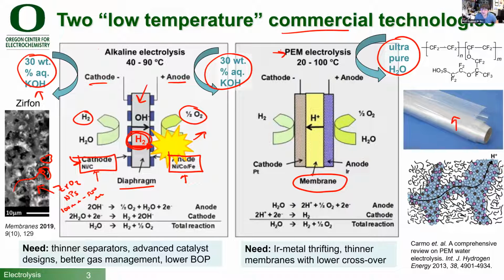It's a polymer that's used in proton exchange membrane electrolysis because it has strong acid groups bound to a fluorocarbon backbone. And those strong acid groups create water channels that are inside the pores here of this plastic membrane. And those water channels have mobile protons in it. So this is a solid state proton conductor with very high conductivity.